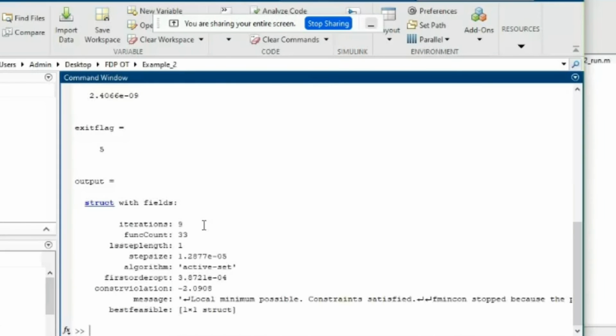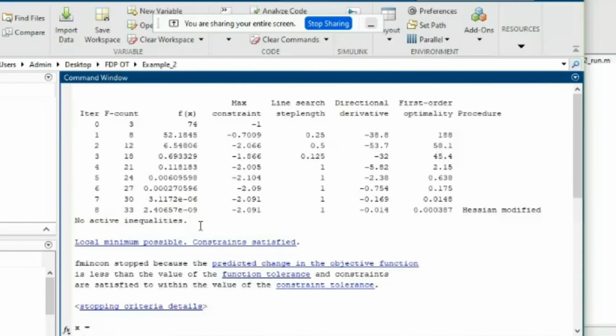So this is the way we can write an M file for objective functions and an M file for nonlinear constraints, both nonlinear equality and inequality, and another one is the run file. All these 3 files we have to write, and then we have to solve, irrespective of the methods, for all the 4 types of constraints. So this solver fmincon can be executed, right?